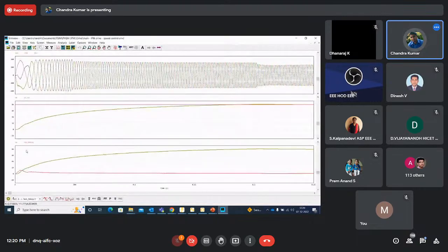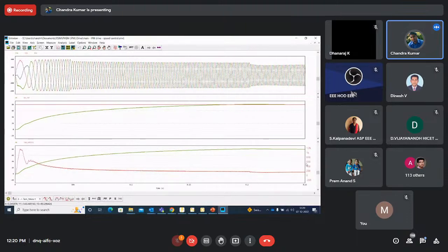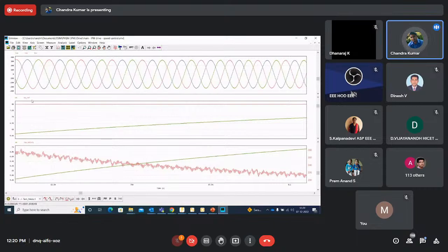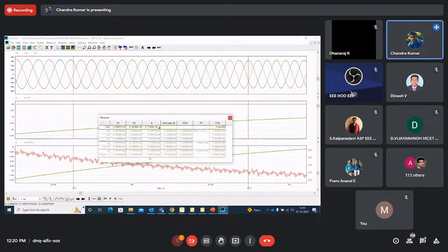Now you want to compare this, and on the y-axis, you can compare this torque versus your speed characteristics and look at your speed. If you want to zoom in, you can zoom in and look at it, and then fit this. So you're fitting these values here and then seeing the speed-torque. So you can measure the values. Is it fine? Yeah.